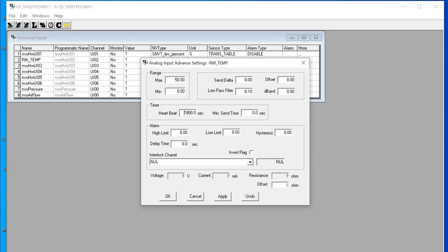This low pass filter smooths the reading. For DDC UI 44, you have experience with the room temperature and the off-coil temperature. Sometimes the sensor has a problem. Last time the off-coil temperature was like this, fluctuating very heavily. This is a sensor issue, so better don't use that. Maybe change to another one.